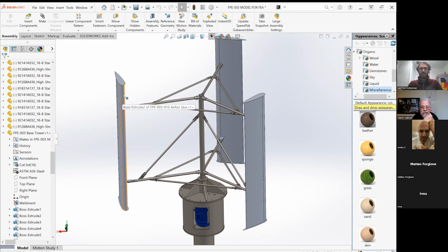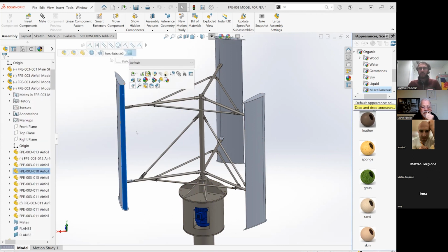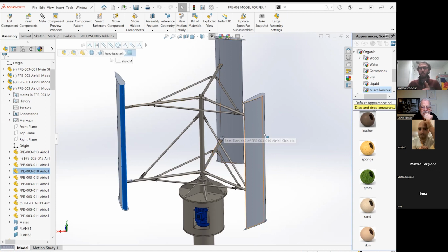For example, if this one is heading straight into the wind, it has the least amount of drag out of any component in the system, and the others will have more, but in any position around the clock as you rotate, it's continuously changing. You have three of them. So you have a continuously changing coefficient of drag and coefficient of lift, basically, as it rotates around.